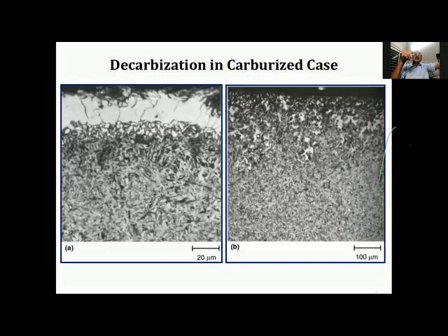We all know that the recirculating fan has two bearings. The upper one is a normal bearing which is outside the shell of the furnace. The lower one is inside, so that tends to get overheated and it can fail quickly. To keep it running for a longer time, a cooling jacket is provided using either air or water. So if by chance for a period of time the jacket punctures or cracks, then water will go into the furnace and the water vapor is highly decarburizing in nature.